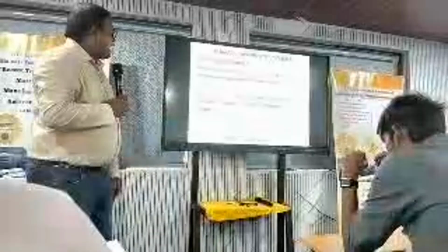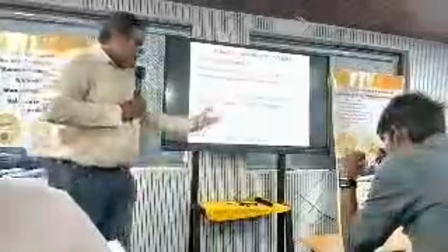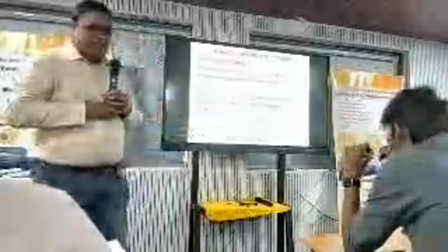It is adding additional layers. Let me show the figures. Let us assume we have a foundation, say a machinery foundation. It has a certain plate thickness and some stiffness, a bottom plate thickness. So if you want to reduce the vibration energy on the structure, we have to decide what kind of viscoelastic layer. Once we have found that property, it has to be bonded on the structure, and above that one more metallic layer you have to bond.